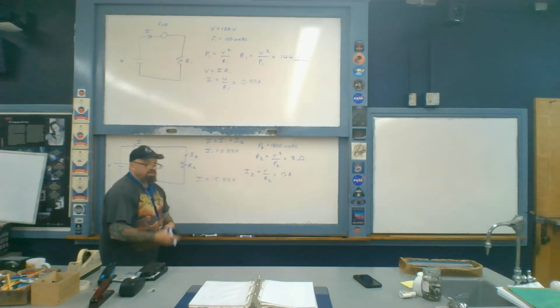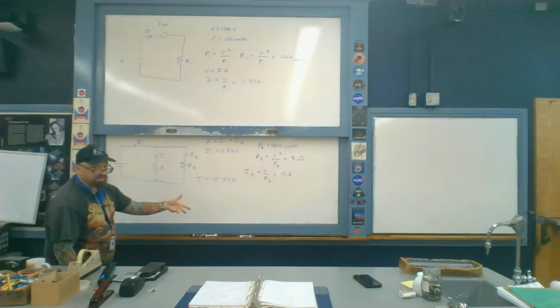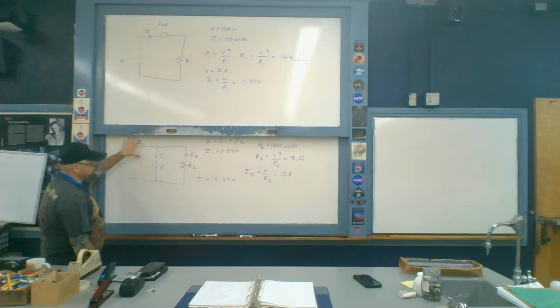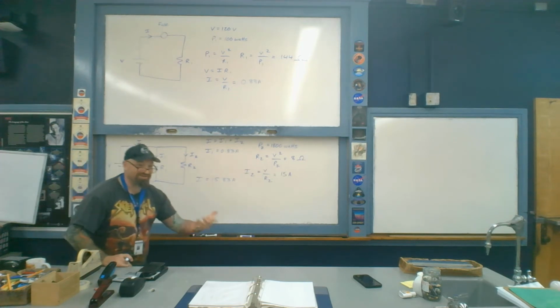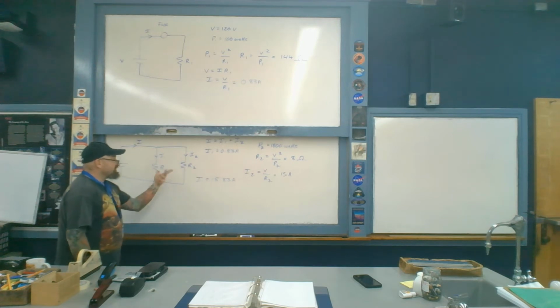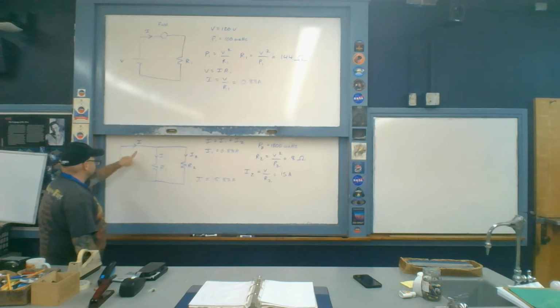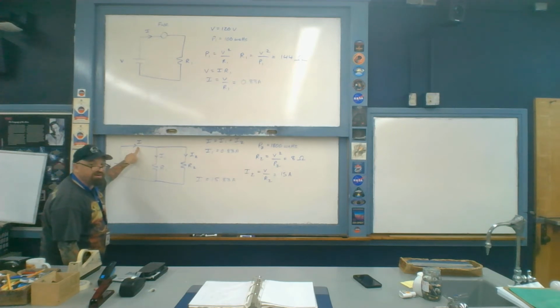Like so. The greater the total amount of current that is being drawn in a circuit, therefore, the hotter essentially the wires heat up due to the resistance. So as the wires heat up, as you draw more and more current, then you start to run the risk, for example, of say right here, melting your wire or ultimately causing something to catch on fire. Obviously, you don't want to have that happen.